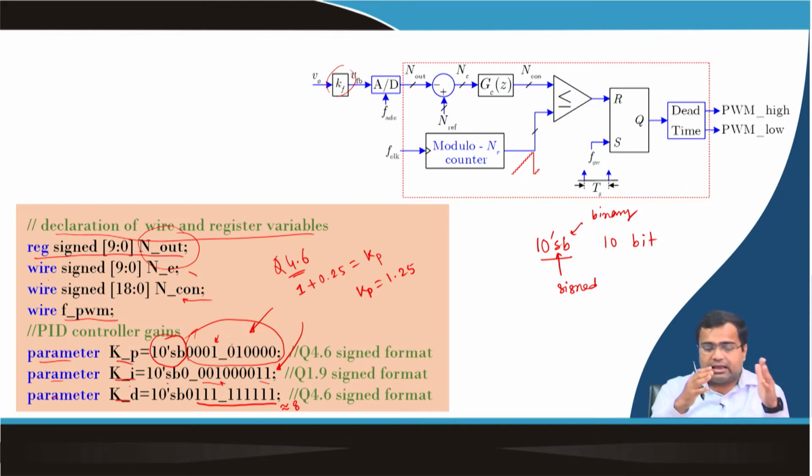But remember these are controller values where there are other scaling factors. It is not the actual one; whenever we did the MATLAB simulation, we have not considered the voltage feedback gain, current feedback gain, and other factors. So, we have to consider them. Now, we will bring back our MATLAB model again, and we will put in those real scaling factors and simulate, and in the subsequent lecture we will see how the simulation result compares, whether it is different from the experimental result or they are close. We want to discuss that, but these are the values.